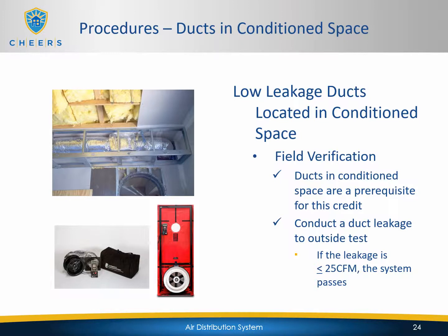So for low leakage ducts in conditioned space, obviously the ducts in conditioned space is a prerequisite for this credit. And then duct leakage to outside has to be completed on the system as well. We talked about duct leakage systems and testing earlier, total duct leakage and duct leakage to outside. So for this particular credit, there has to be a duct leakage to outside test that takes place. If the leakage is less than 25 CFM, then the system passes.